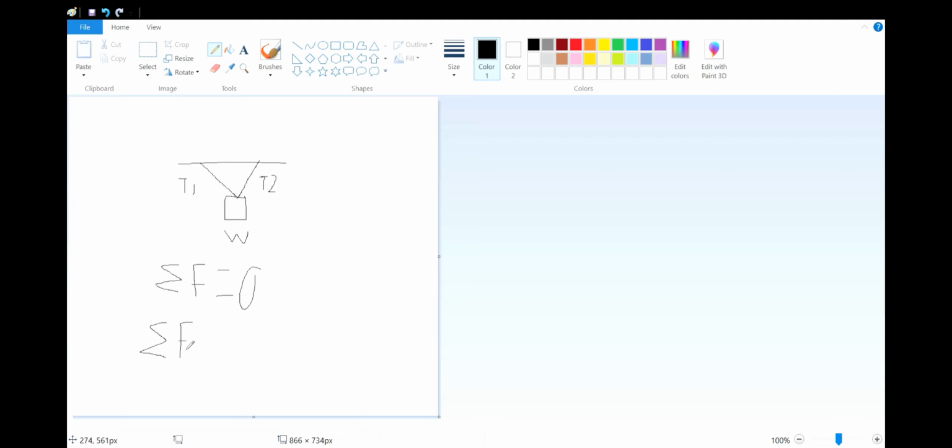We can break this down further into the x and y components because forces are represented with vectors. We know off the bat that they add up to 0. However, we would like to find the individual forces and not simply their sum. We first measure the angle of tension 1 and tension 2 with respect to the ceiling they are tied to.